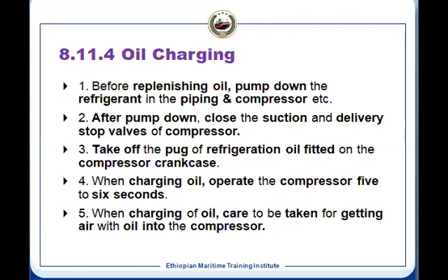So in that case, what will happen? You operate the compressor for 5-6 seconds, very little time. Once you operate, your suction valve is shut, so that the suction pressure, crankcase pressure will reduce. Once the crankcase pressure is reduced, now oil can be charged to the compressor. Suppose this is a compressor, and we have shut this. We run this compressor 5-6 seconds. Then there is no flow from the suction, so there will be a low pressure created, and we have a charging point with the valve.